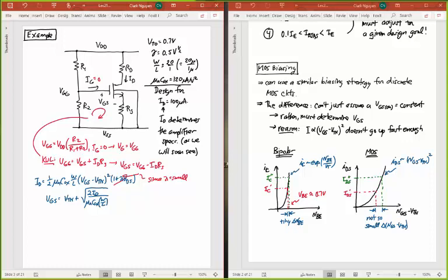If you look at this, this part here is basically the amount of voltage beyond which we create that inversion layer in the MOS transistor. All we need to create the inversion layer is VTN. But usually we have a little more voltage to get a certain amount of current, which is dictated by this equation. So this part here is often called VOV, which people term the overdrive voltage. You're going to see that terminology.